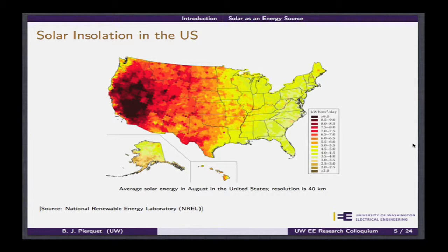In a lot of the very, very warm climates, the photovoltaics tend to become less efficient. So when it's Southern California in the middle of the summertime and it's 100 degrees on top of a building, those solar modules are substantially less efficient, at least for the silicon ones that are most popular, than they would be if it was northern Minnesota in the winter, 40 below zero. And so the actual energy generation capability per location in the U.S. has a much more complicated structure depending upon the time of the year.